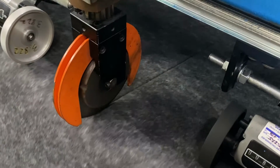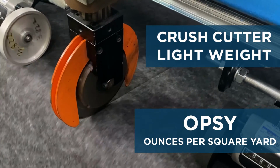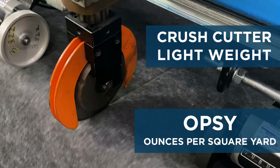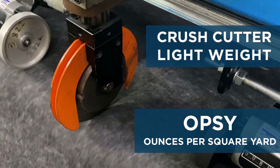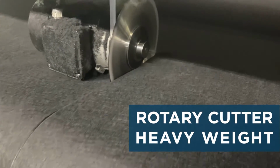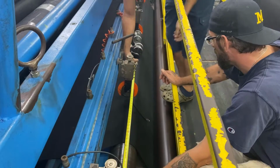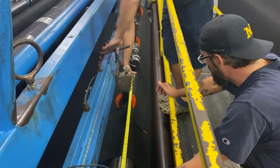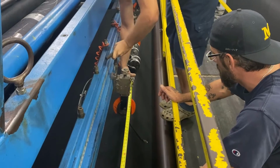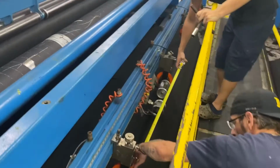We have 2 options of cutting depending on the weight of the material. We consider lightweight products to range from 3 to 10 OPSY, or ounces per square yard, and would be assigned to cut on the crush cut system. Heavyweight products range from 11 to 36 OPSY and would be processed through the high-speed rotary cutting system. Blades will be set to specification by using a tape measure and adjusting the cutters to the requested set point and then tightening them into position.